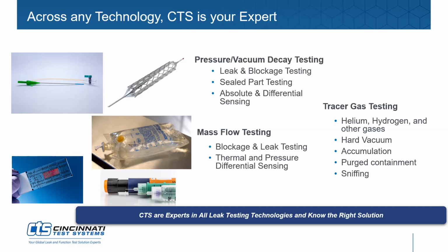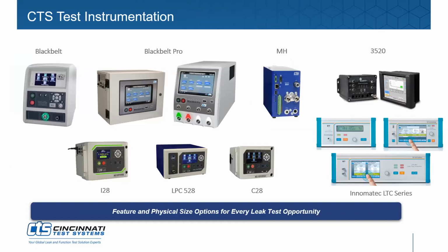Then finally, for non-disposables, typically durables that are implanted, we offer tracer gas technology, which is the ultimate in leak testing. But of course, with the consumable tracer gas, helium or forming gas, the cost of this and the cost of that equipment oftentimes makes it cost prohibitive, and process cycle time prohibitive, to do with single-use disposable devices that are typically made of plastic.